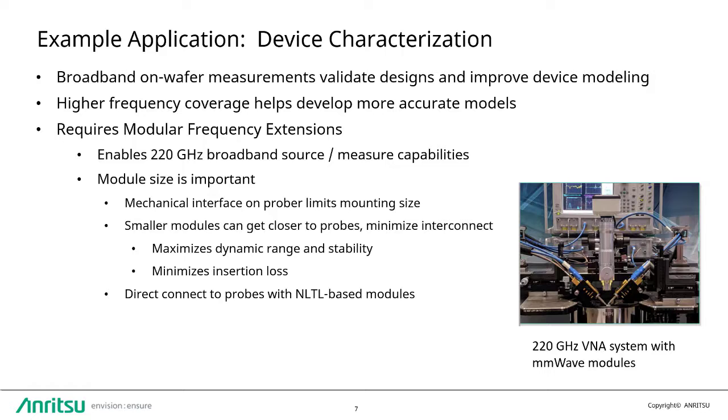An important application example where modular architecture is a major advantage is in device characterization. Device modeling requires accurate, high-frequency measurement data to improve the behavioral predictions of models used in design. Models developed with narrower frequency sweep data sets may not predict oscillations or other unwanted device artifacts in the actual design that models developed from a wider frequency span data set may uncover.